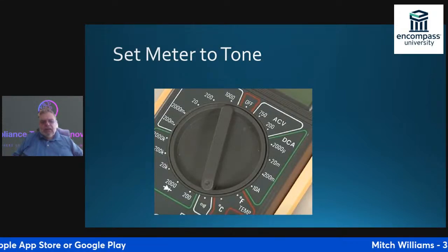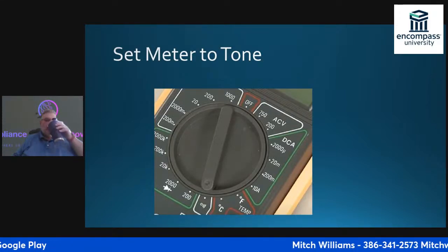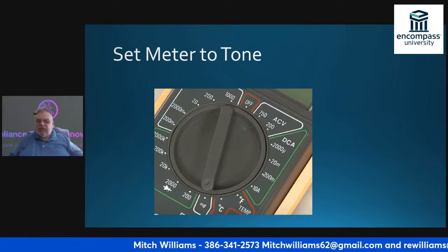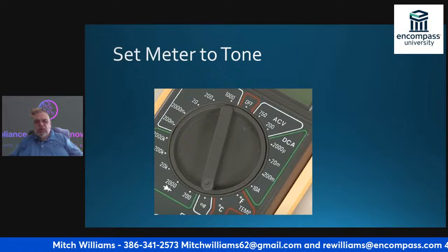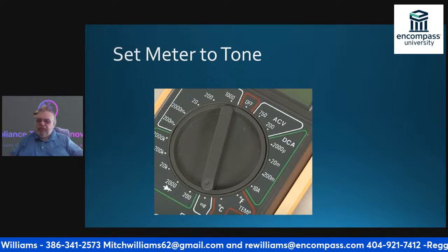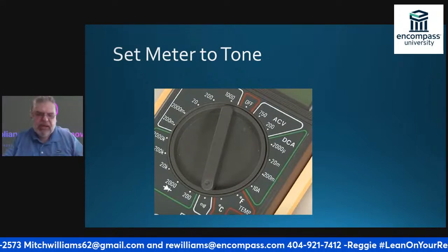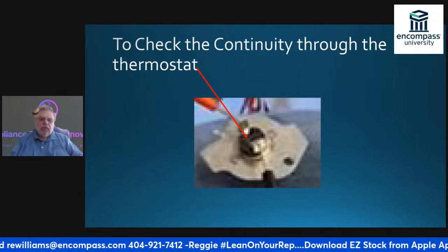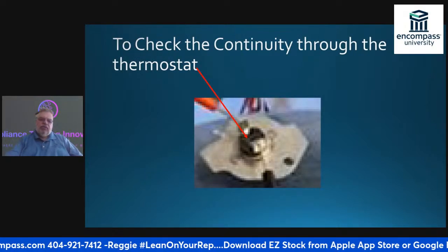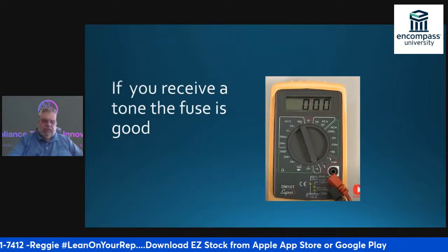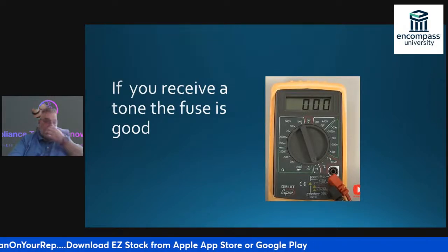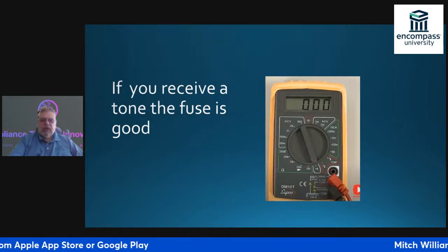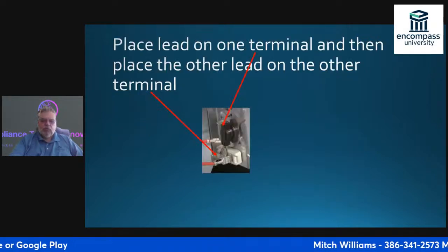I put mine on the tone, and I checked across that, and I had no tone. That tells me that thermal fuse is bad. If I have a tone, then I have to go to the next thing on the list, which is to check continuity through the thermostat. There we go, I got ahead of myself here. If you receive a tone, the fuse is good. If you don't, the fuse is bad and you have to replace it.